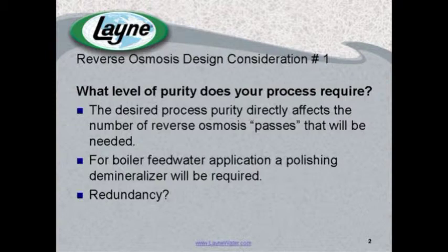Do you have the ability to stockpile reverse osmosis water in a large tank? Or do you have to have 100% availability, 95% availability? What's that look like? Because reverse osmosis systems do require system maintenance. You'll have to take elements, perhaps passes, perhaps stages, out of service from time to time for cleaning and maintenance. And you want to have all that accounted for right up front.